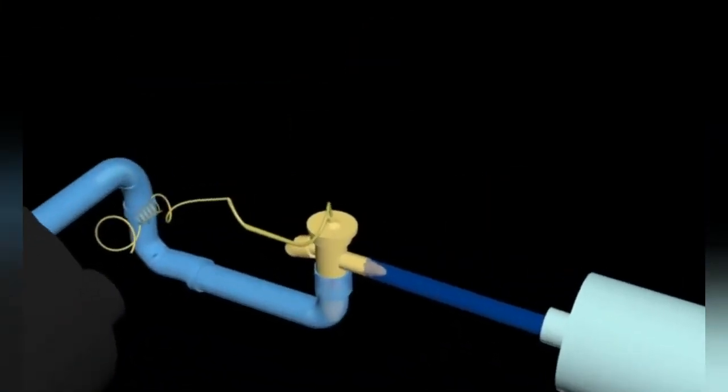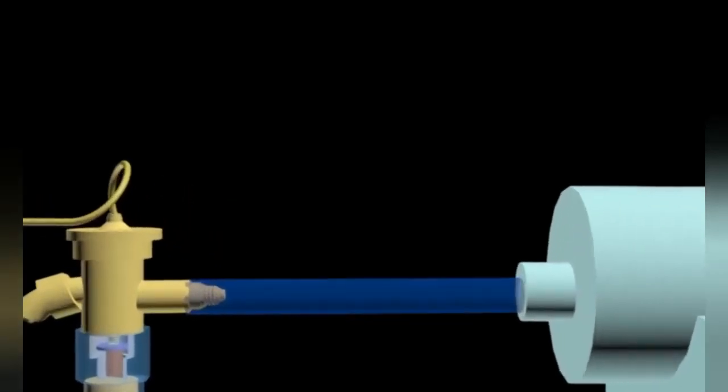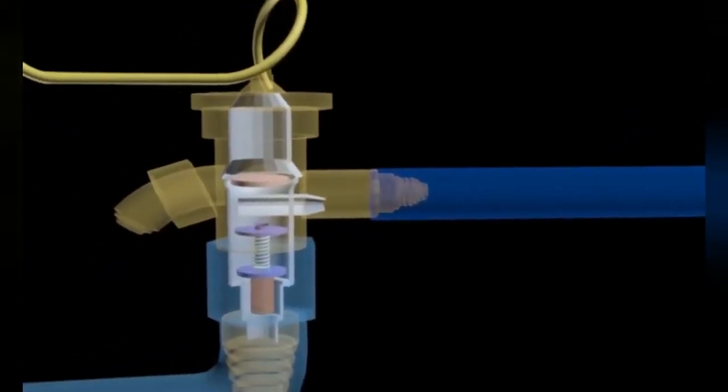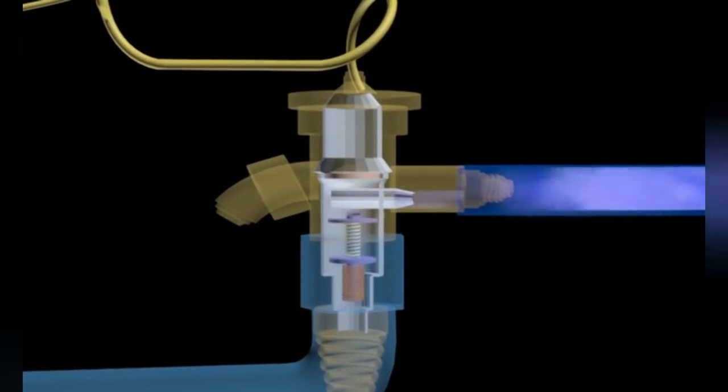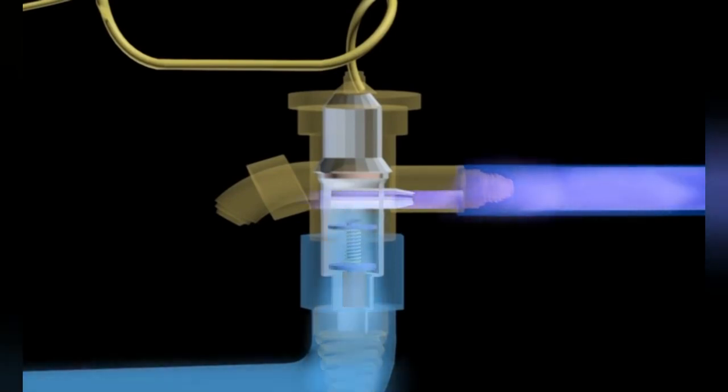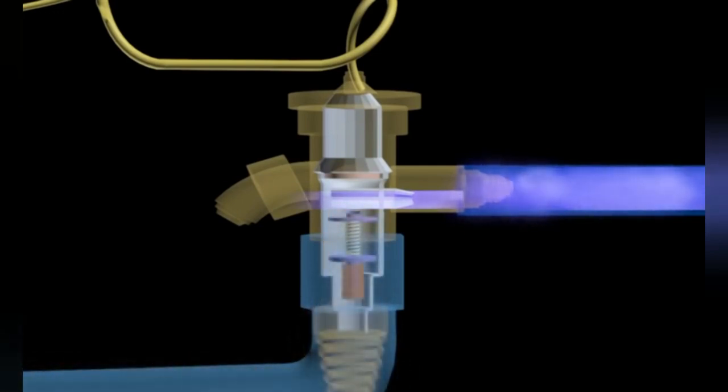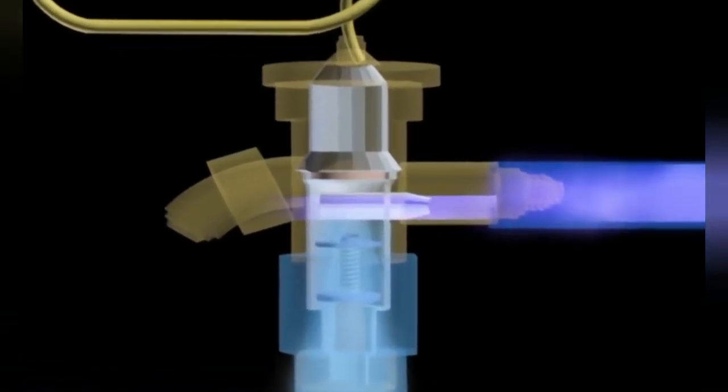Expansion valve. The expansion valve serves to reduce the pressure and control the flow of refrigerant going into the evaporator. When the pressure of the refrigerant has declined drastically, the temperature will drop dramatically, which is lower than the chilled water temperature. In a centralized system, a thermal expansion valve (TXV) type expansion device is used.